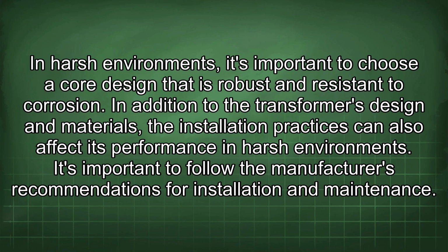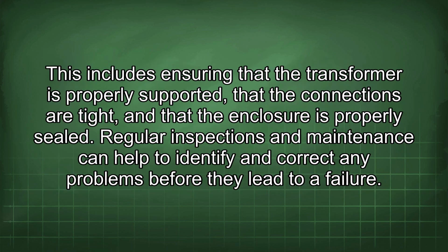In addition to the transformer's design and materials, the installation practices can also affect its performance in harsh environments. It's important to follow the manufacturer's recommendations for installation and maintenance. This includes ensuring that the transformer is properly supported, that the connections are tight, and that the enclosure is properly sealed. Regular inspections and maintenance can help to identify and correct any problems before they lead to a failure.